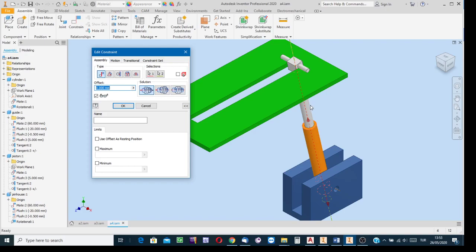It is really important. You see, although the axes are in alignment, the piston is to be displaced in the direction of the axis of the cylinder, so insertion type, no. Insertion type constraint positions the axis of one component in alignment with the axis of the other, but the motion is impossible. Sliding will not occur, it cannot have sliding type displacement.